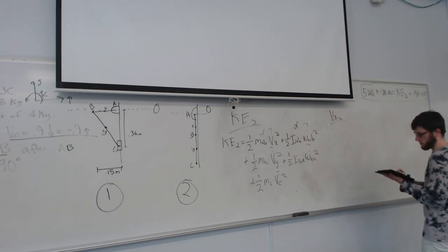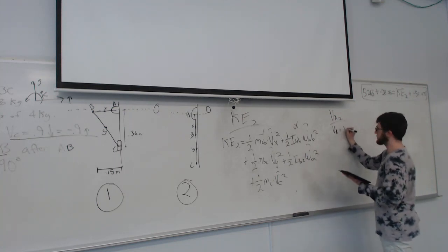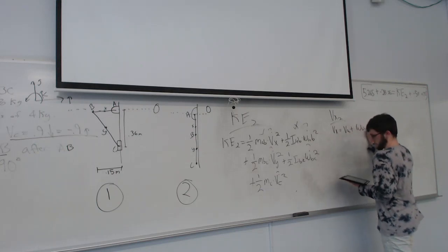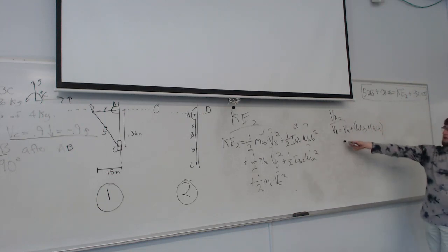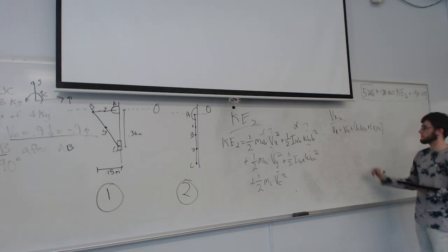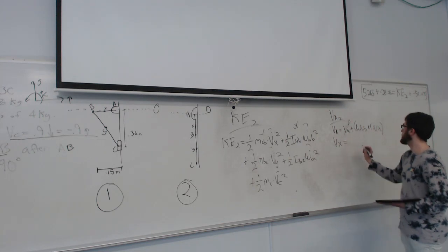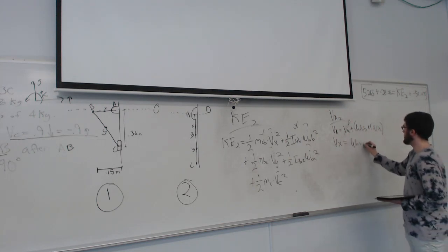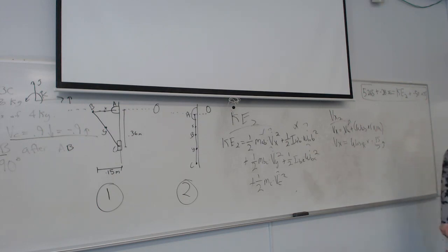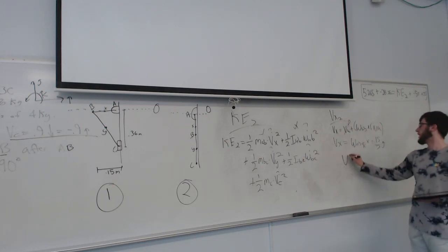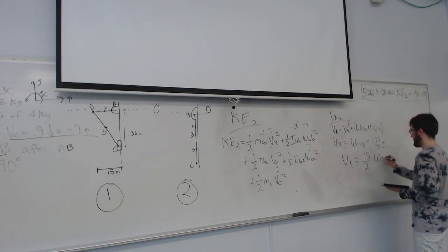Velocity of x at point 2. So looking here, velocity of x is going to be equal to the velocity of a plus the angular velocity crossed with the position vector. Velocity of a is still 0, so velocity of x equals omega AB crossed with this, the position vector. Velocity of x equals 0.15 over 2 times this.